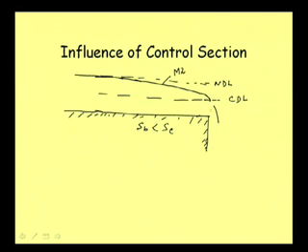Now this profile is moving like that and it is meeting the CDL line normally at this point. At the downstream point, this is also called brink depth or end depth. From a practical point of view, as hydrostatic pressure is not prevailing here, that assumption was there for hydrostatic pressure. Some investigators analyzed that the brink depth or end depth is not exactly equal to critical depth.